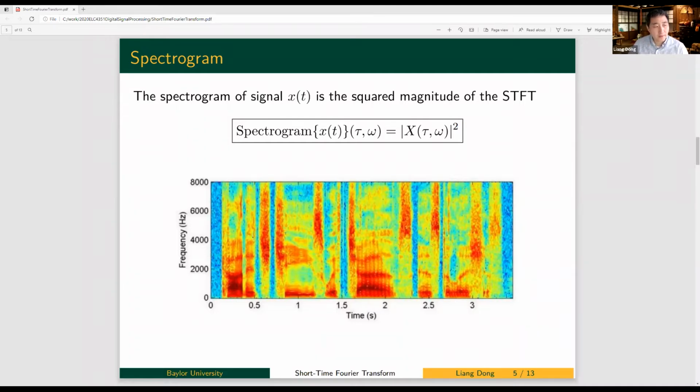It's very popular in the radar system. In radar system, I'm going to sweep one angle of the space, and this frequency we can use as a Doppler frequency. The Doppler frequency basically, if there is an object flying towards you, the Doppler frequency will be higher. If it's flying away from you, Doppler frequency will be lower.